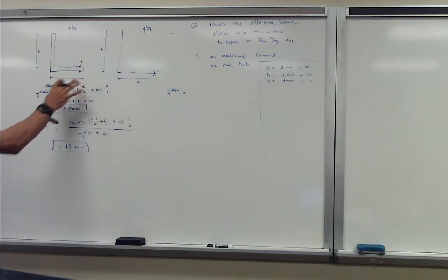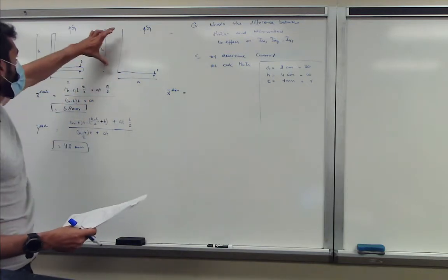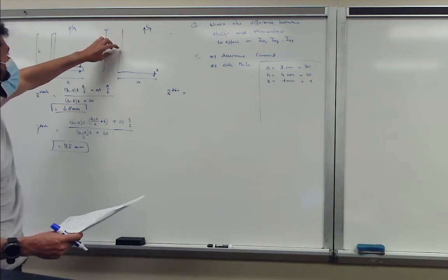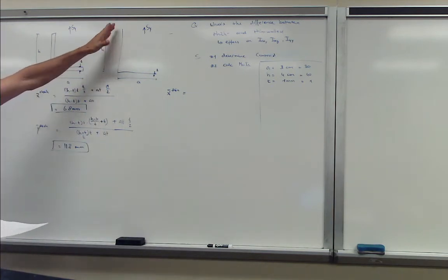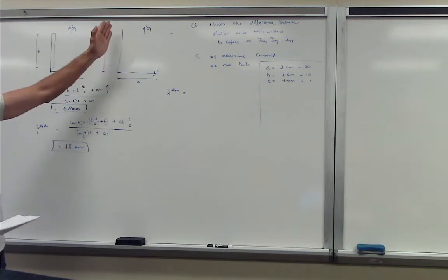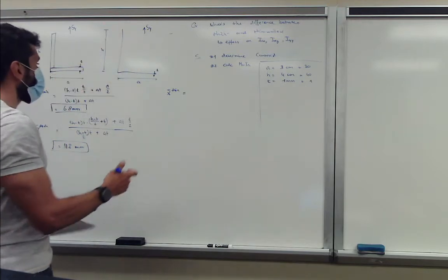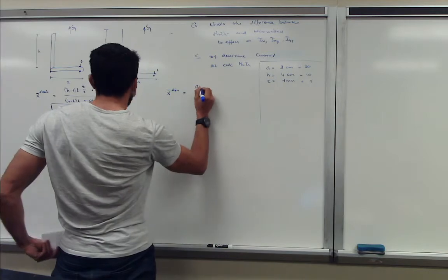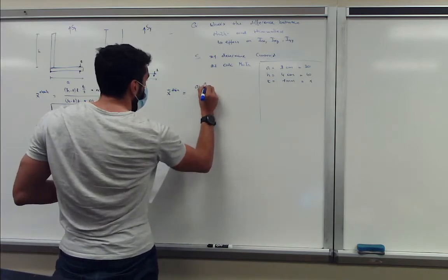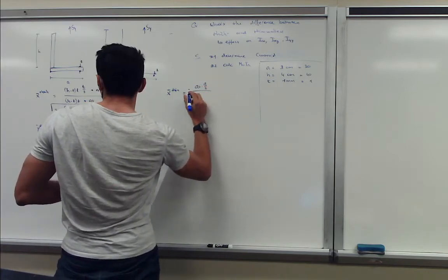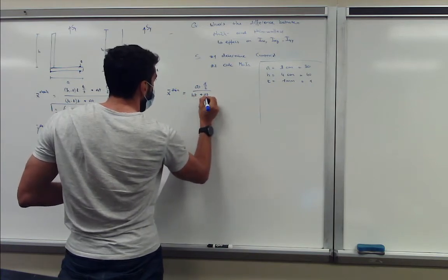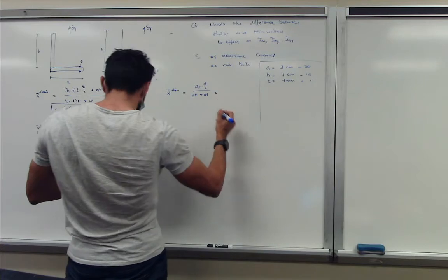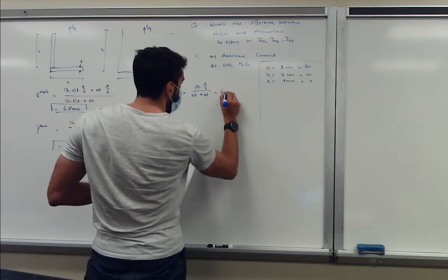So this whole term or this section basically drops out because you assume they coincide with each other. So you assume that the y-axis basically coincides with the vertical flange. So in this case, you only get AT multiplied by A over 2 divided by HT plus AT. And if you do that correctly, you get 6.43.